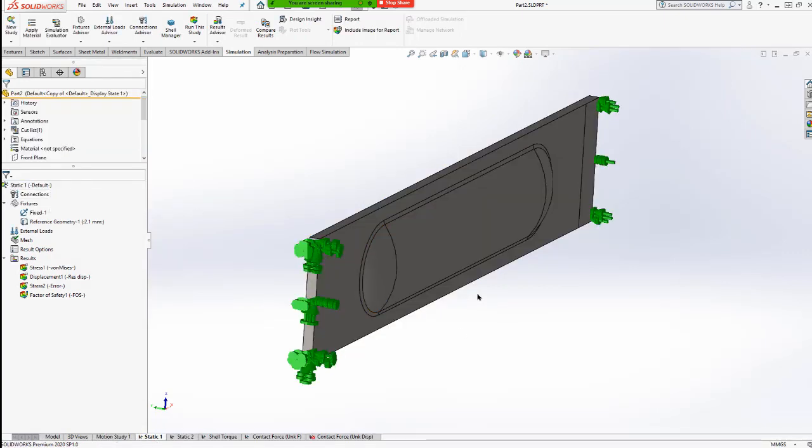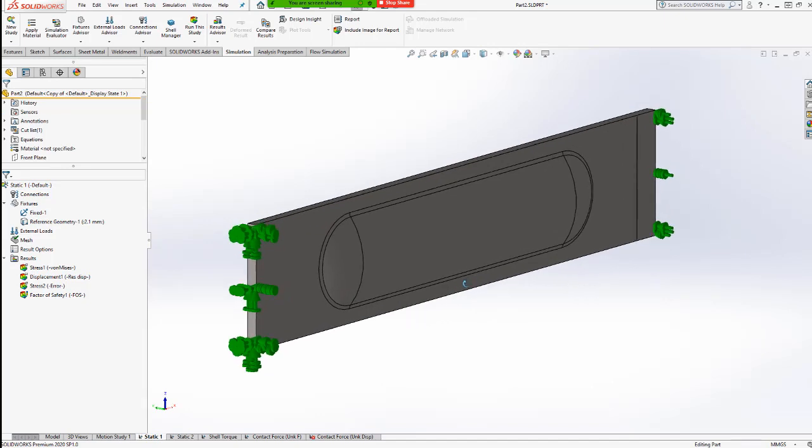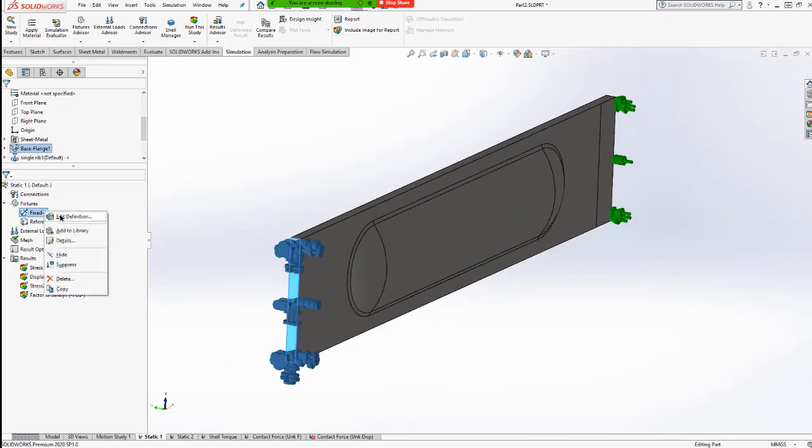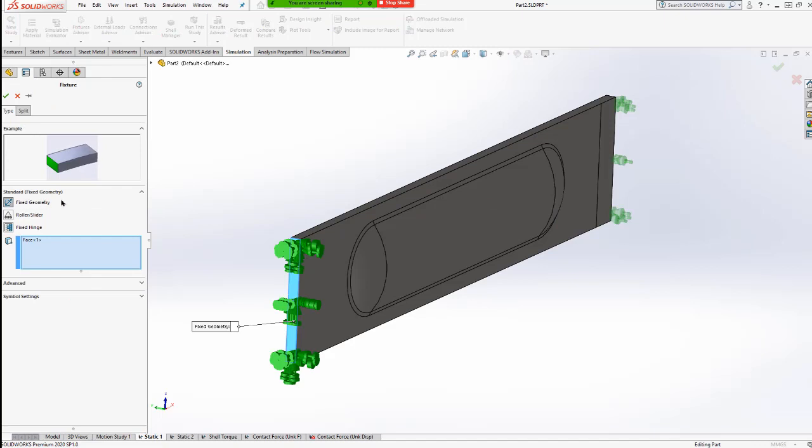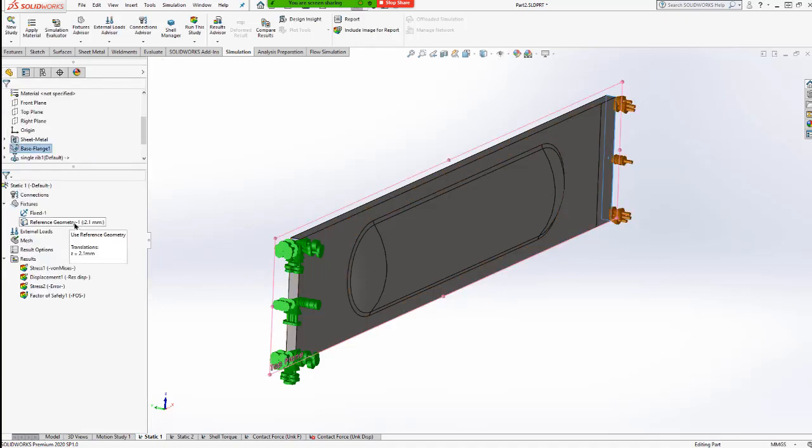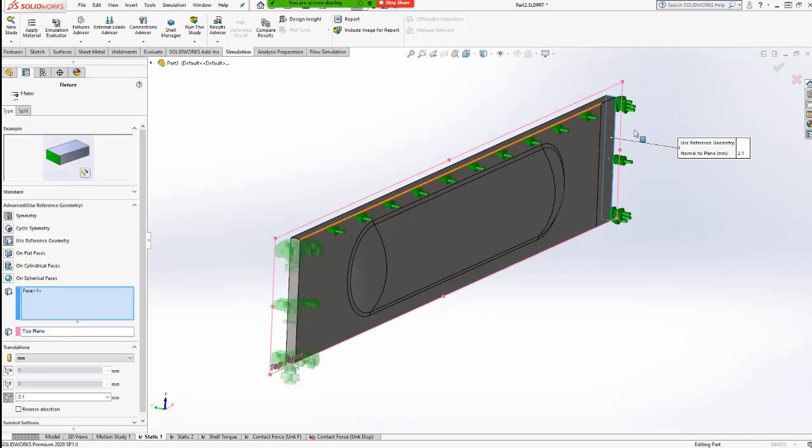All right, and I'm going to start by going over our first ribbed solid. This is as per the first example of what we saw. So here I have our first fixture, and since it is a solid, we will not have our immovable option. It'll just lock down our translational motion here with our fixed geometry, which is what we want, right? If we're allowing this to rotate, then there's technically no torque. It's just giving out with whatever forces or displacement is pushing our part out from equilibrium, or where it's sitting in free space. And the fixed geometry allows us to actually get a good reading because it's sitting there. It's going to interact with whatever force is going on over here.